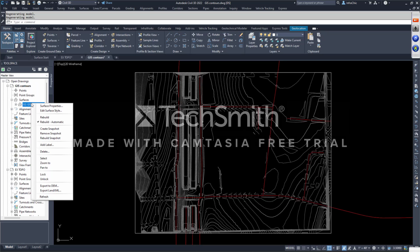Again, right-clicking on the surface object within the tool space, you'll have other options like pan to. You can lock it so it can no longer be edited or moved by accident. You can unlock it, and you can export it to a DEM file or a LandXML file. This is important. The DEM, not so much, unless you're dealing with LiDAR data and it's really large, okay?